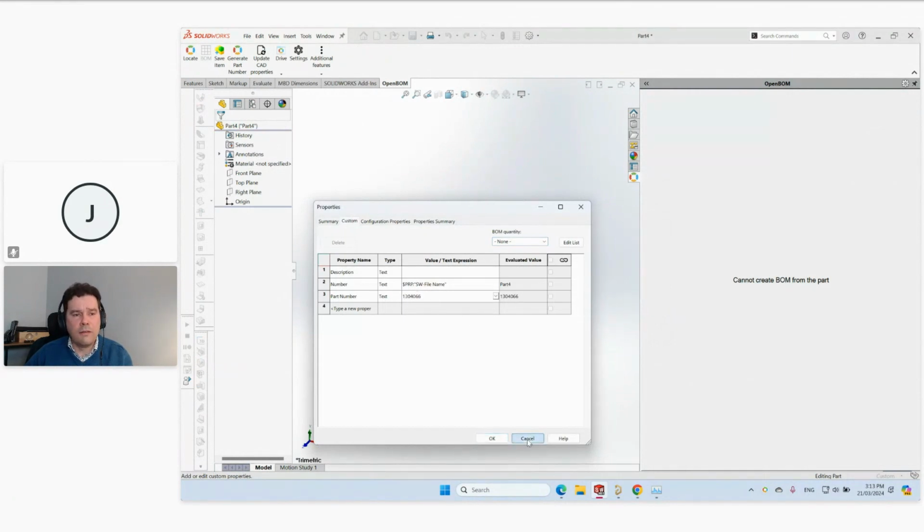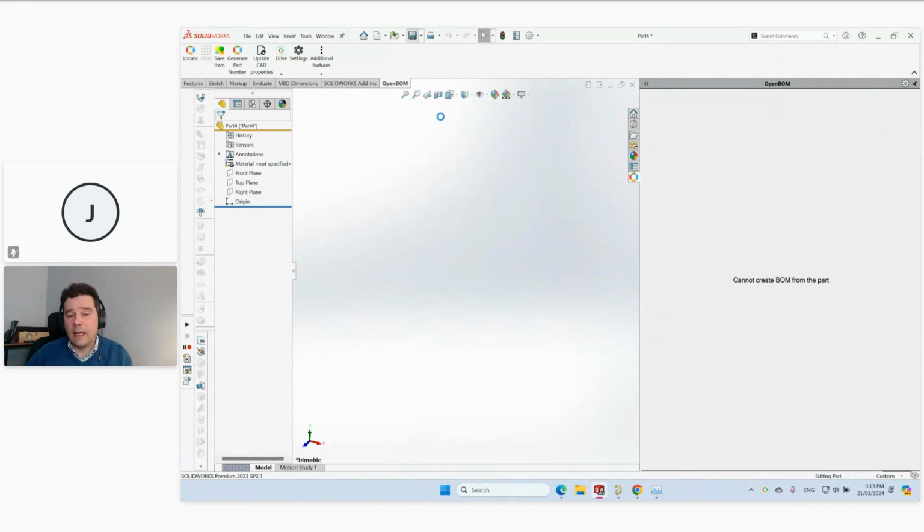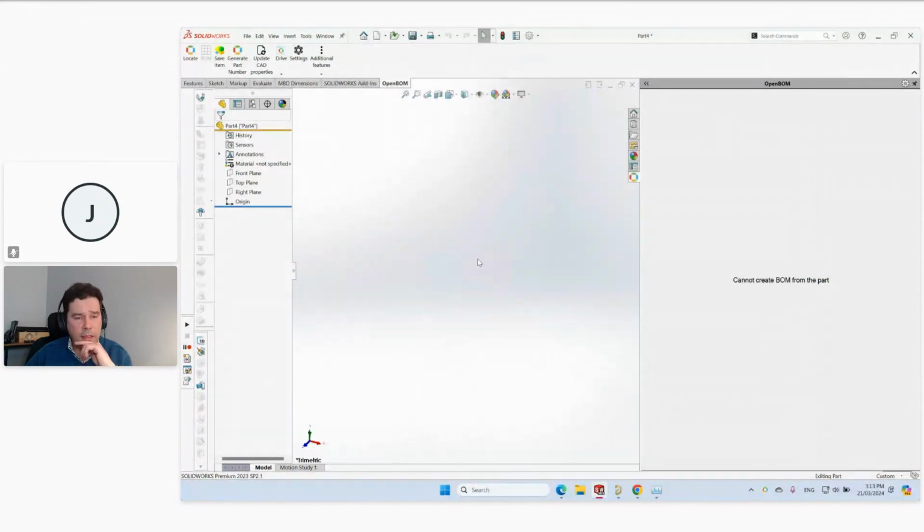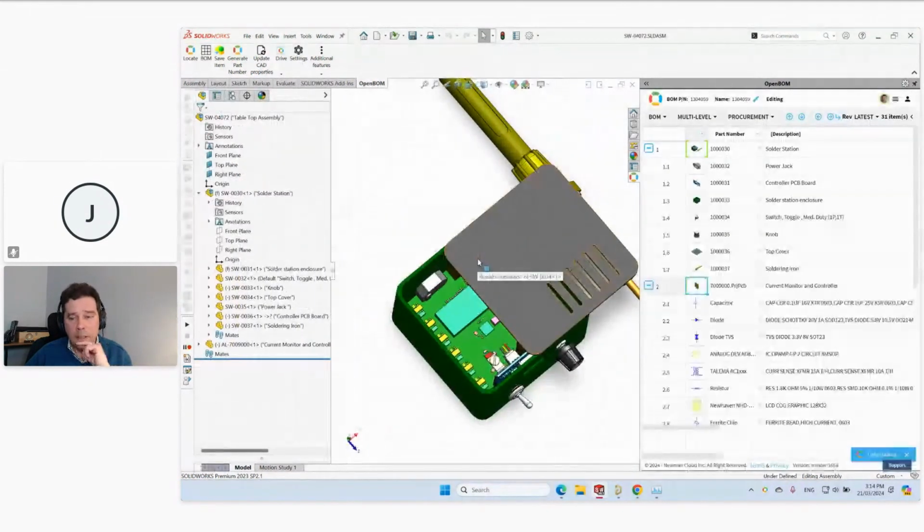If you save your parts with the same file name as the part number, you can just save the file name, or you can put a different counter there or a drawing if you use different document numbers from part numbers. So we support all those different methods, but having unique numbers is a good practice so you can achieve accurate bills of materials, and you can combine, for example, information from ECAD and MCAD together if you have a cross-reference part number to bridge the data together. Okay, so